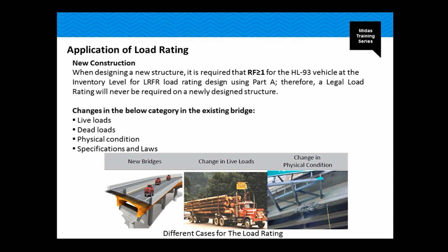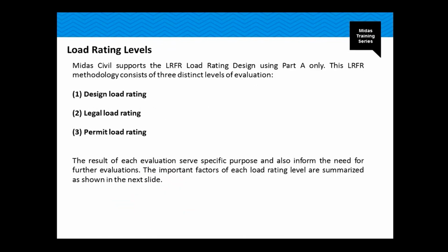So it changes in the below categories in the existing bridge: live load, dead load, physical conditions, specifications, and laws. Those are the cases for the load ratings, and we're gonna go over each one of them. Midas Civil supports the LRFR load rating using Part 8 only.